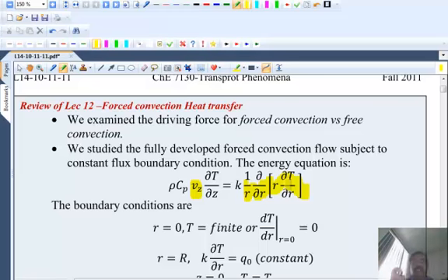So you take the energy equation subject to that assumption of the velocity field and temperature field, simplify it. How does Comsol do that? Comsol will solve all the terms in every equation. When you say 2D, of course it drops the third equation. But in those two equations, you will have derivatives with respect to z also, right? Those will be dropped because there is no variation in there. Okay, so Comsol doesn't make the simplifying assumptions that we make to get an analytical result, but those terms will naturally die out because there are no gradients in there. Computes a gradient, it becomes 0. Okay, so in this case, we simplified it specifically for a one-dimensional problem.